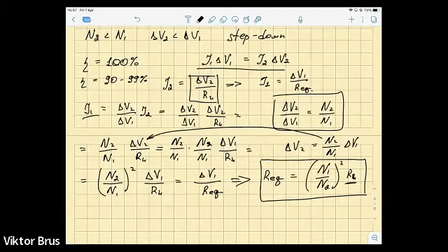So with this, I finish our discussion of AC circuits, and summarizing, need to highlight that there is a fundamental difference of charge transport, AC charge transport through active and reactive resistors. So active resistor is just regular resistor, which we were familiar previously with in DC current circuits, and reactive resistors are capacitive and inductive resistors. So they cause some phase shift between current and voltage, and obviously when we put them together in electrical circuit connected in series,